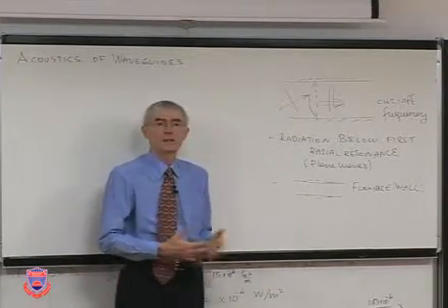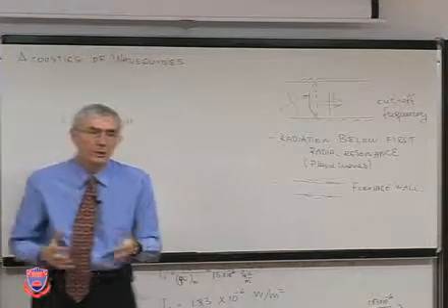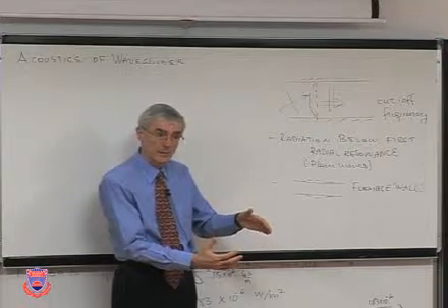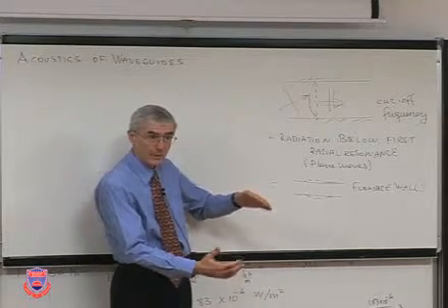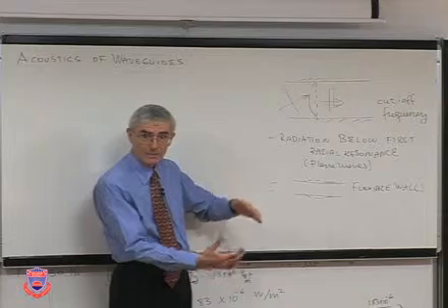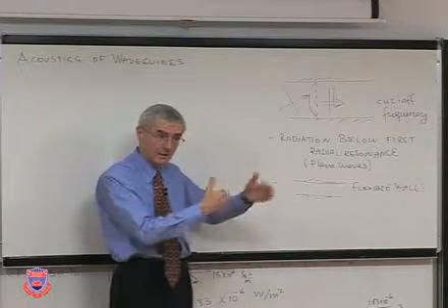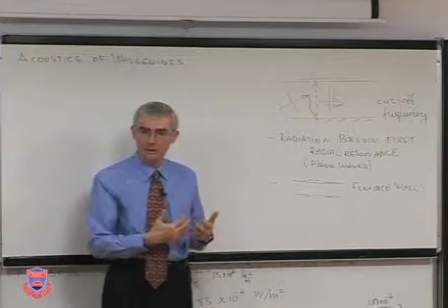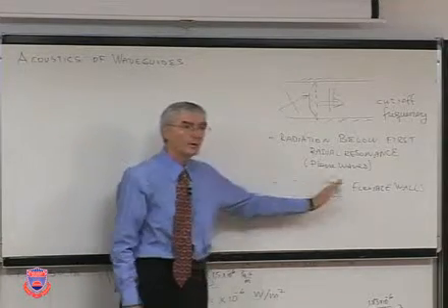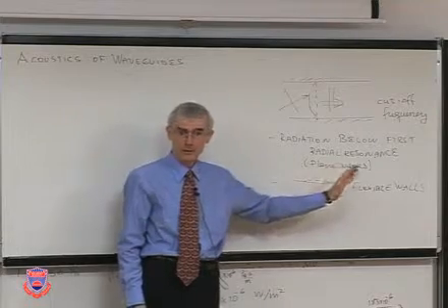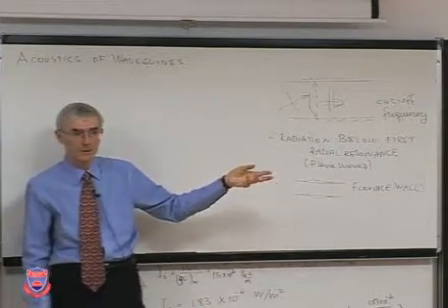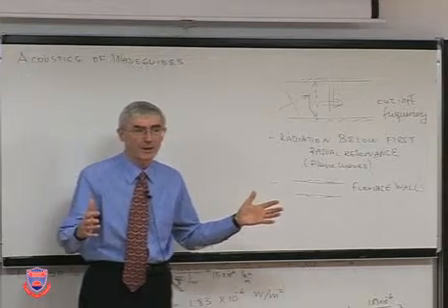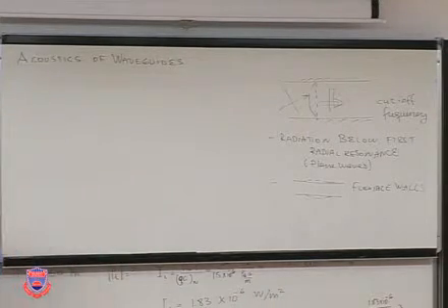Because they have some inertia, some flexibility, it's like an oscillator. And if they flex, what happens? The volume or the area is going to change. If the area is changing, the instantaneous volume changes, density drops. So the pressure equation is going through a transformation through the flexible area. That's what we'll learn. What does it mean? Now, there'll be resonance of the pipe. You hear these sometimes. Okay? So that's the flexible walls.